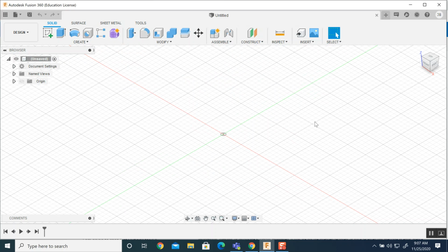It's important. One thing you've got to remember is once you've set it and you haven't drawn anything yet, you haven't clicked on it, you haven't drawn, it's going to draw in the units that it's set for. So if you start to draw something and you realize the units are incorrect, you actually have to close that and start again, but set the units properly before you create your next part. Okay, because as soon as it's drawn, it's stuck with the units that it's in. In other words, you can't change the units once it's been drawn. Okay, all right, at least not easily.